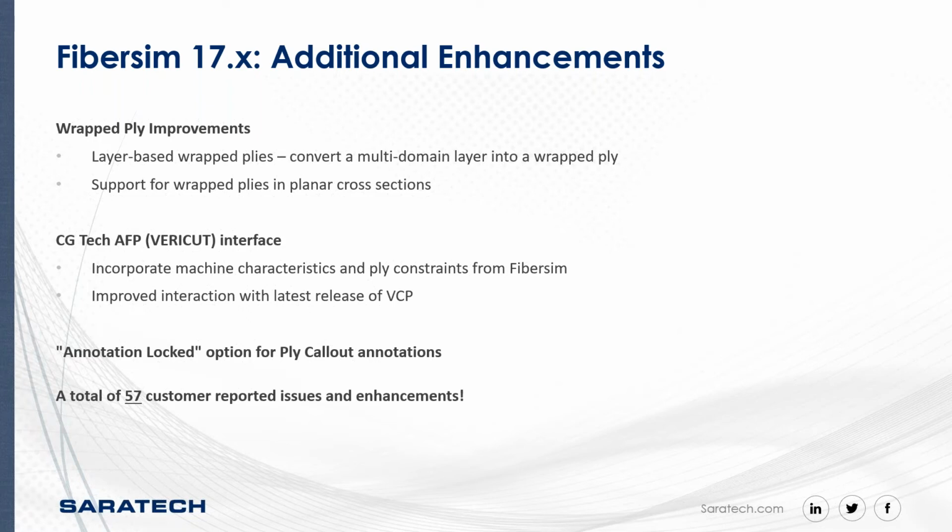And Fibersim also has a very broad set of manufacturing interfaces where we can interface with all of the industry standard tools, be it the various formats that Fibersim uses for exporting 2D flat patterns. You can use the generic DXF or IGES formats. You can also use some formats that are targeted at some of the nesting systems. We also have capability that allows you to export to the various laser projection vendors in all of their various different formats, but we also have automated deposition options within Fibersim that allow you to handle automated tape laying, ATL, as well as automatic fiber placement like AFP.